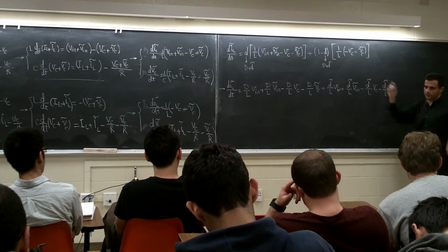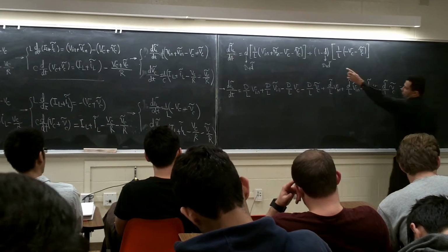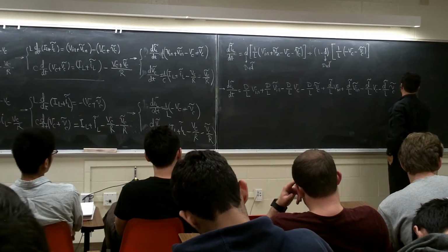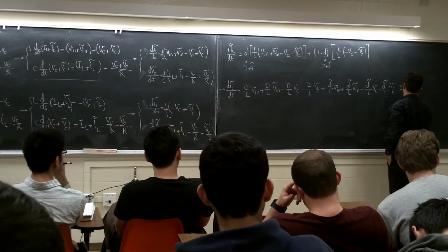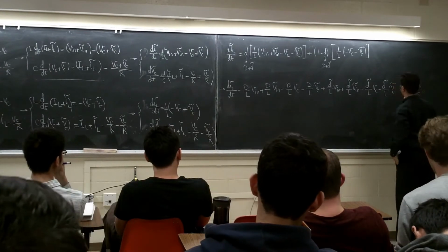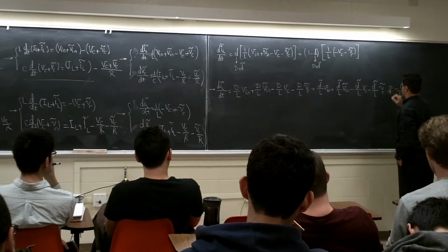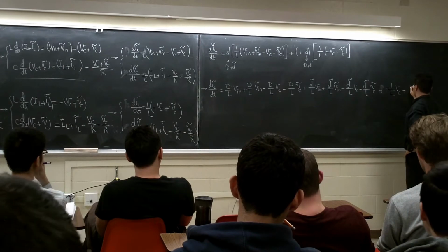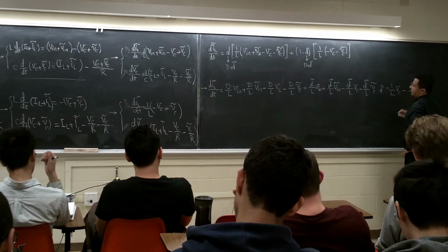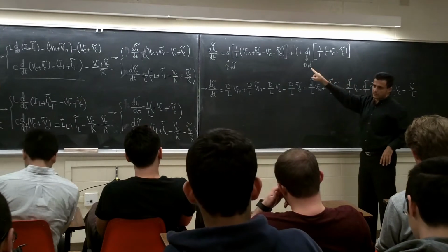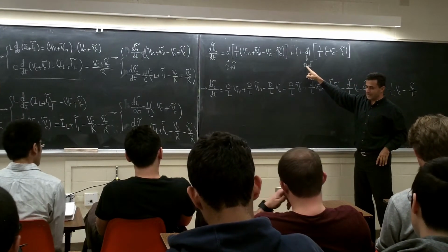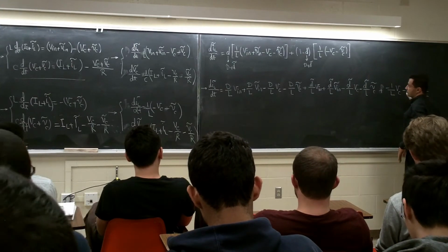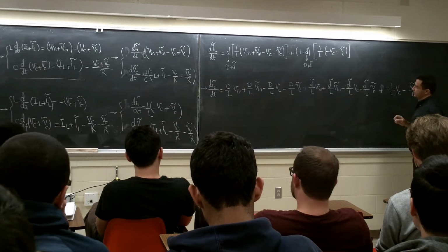Now we need to do the same thing for this side. We start with 1. 1 times this is going to be minus 1 over L Vc minus Vc tilde over L, so I multiplied 1 by this equation, right? Now I should do minus D, minus capital D, so it's going to be plus D over L Vc. Check it to make sure I'm correct.